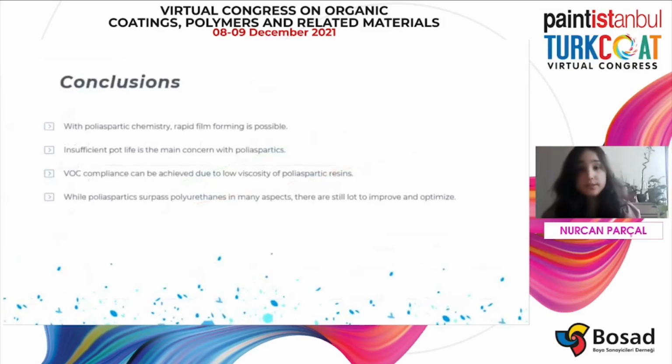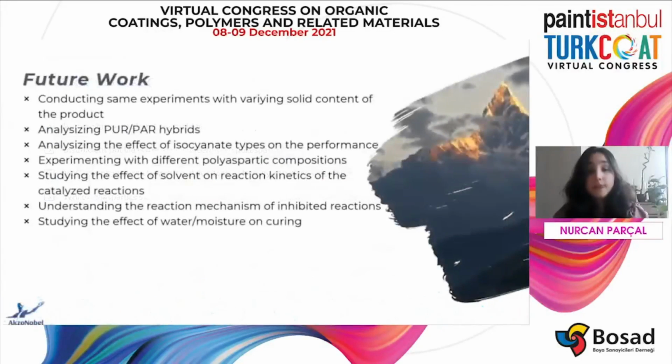As a result of this study, we concluded that with polyaspartic chemistry, rapid film forming is possible, and insufficient pot life is the main concern with polyaspartics. VOC compliance can be achieved due to low viscosity of polyaspartic resins. Also, while polyaspartics surpass polyurethanes in many aspects, there is still a lot to improve and optimize. This study is very comprehensive and has a significant potential to conduct further.